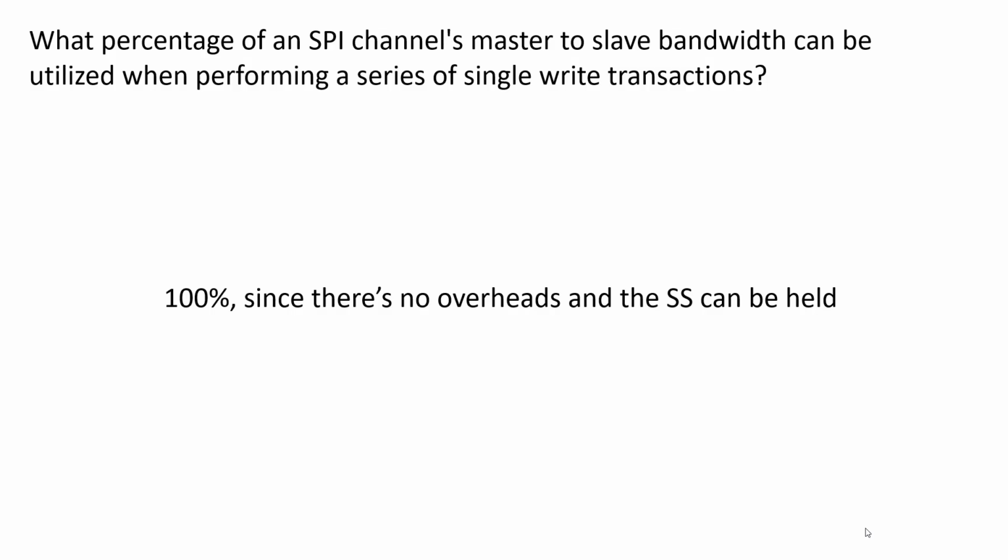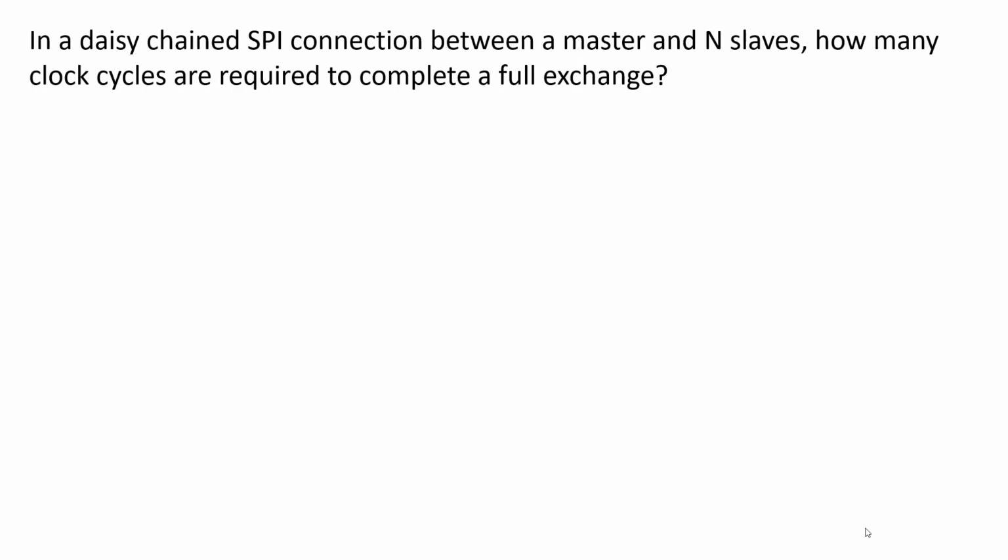Now you might say, as opposed to what? Well, as opposed to UART, where you have a start bit and a parity bit and a stop bit, which effectively steal bandwidth from the data, right? Whereas with SPI, you don't have bandwidth stealing for the control signals.